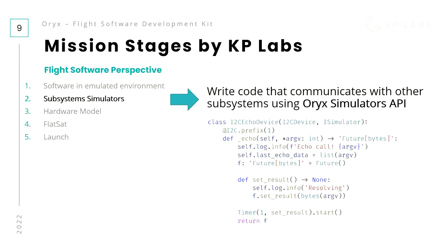So, a short example, I will try to keep the amount of code as low as possible. This is Python code. The simulators are written in Python, so it's a very easy language to learn and to use. We have a ready API in Oryx, so you can easily define new simulated devices. We currently support I2C, CAN, simple GPIOs, UART, and to some extent SPI. There's an asterisk with SPI because it depends on the actual protocol, but we can do that as well.